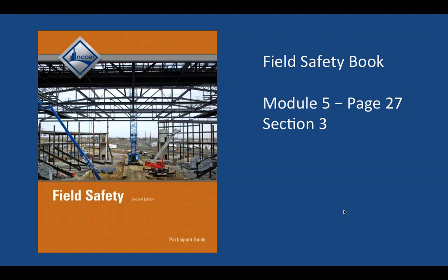That's why it's important that we have that manual and all the warning decals, instruction decals, and all the instructions for operator use. They must be legible. Also, we have to be familiar with the employer's work rules and any government-related standards like OSHA standards. And then an operator has to be able to demonstrate their understanding, operating the associated aerial lift during training in the presence of a qualified operator.